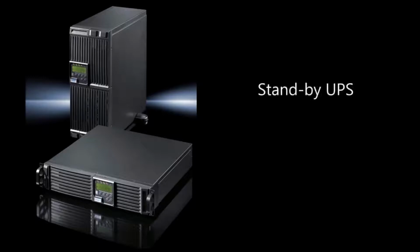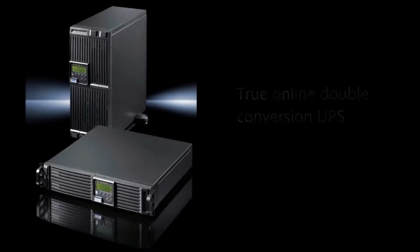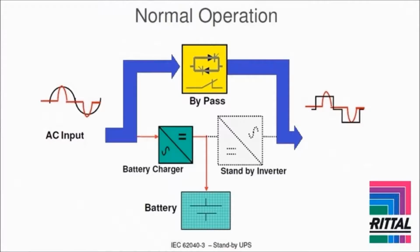Standby, or offline. Line interactive, or interactive. True online, or double conversion. The standby, or offline, UPS has a square wave output, which is often referred to as a modified sine wave output. When utility power is available, it is supplied to the connected equipment through a bypass switch, and the AC input is simply passed through to the output.